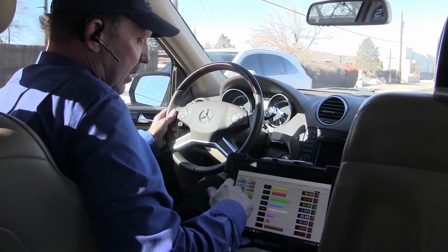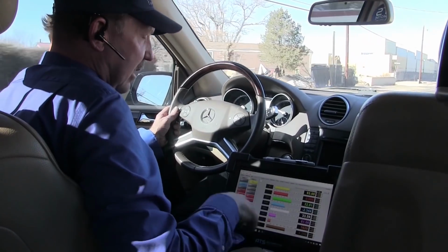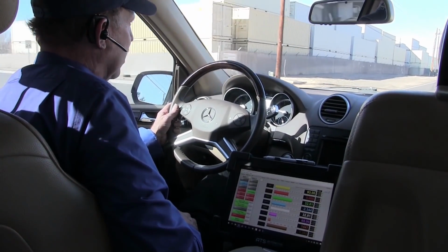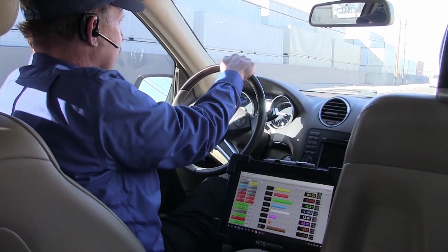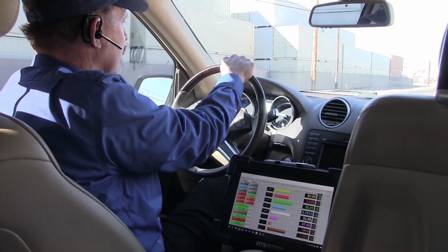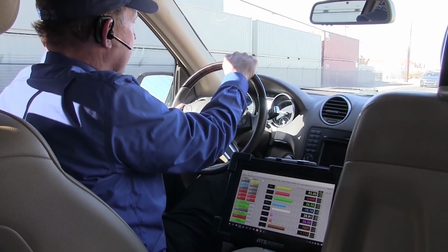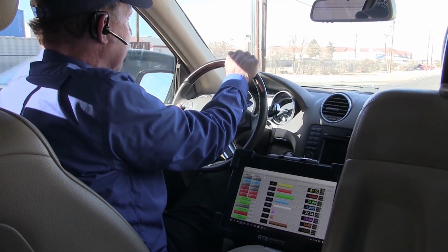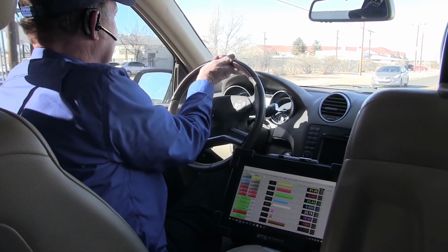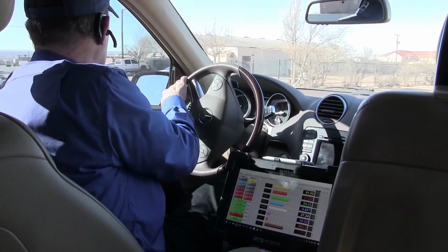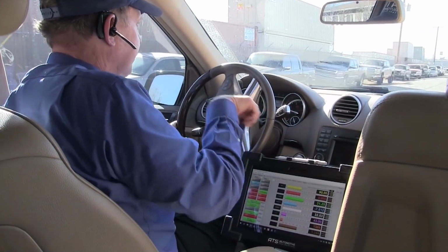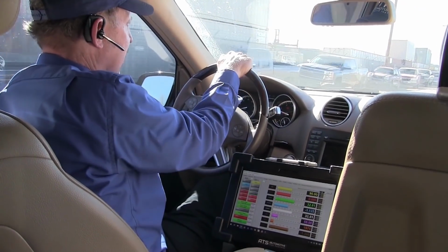It didn't feel like it pulled right. So right here we can take a look as we're driving, and it gives us a different look. But what's really important is the way we plot the graphs, and we can compare those graphs to figure out what's really wrong with the car. Because a problem like this could either be in the air side or the fuel side. And that's all I'm trying to figure out right now. And now I can see that the problem is on the fuel side.